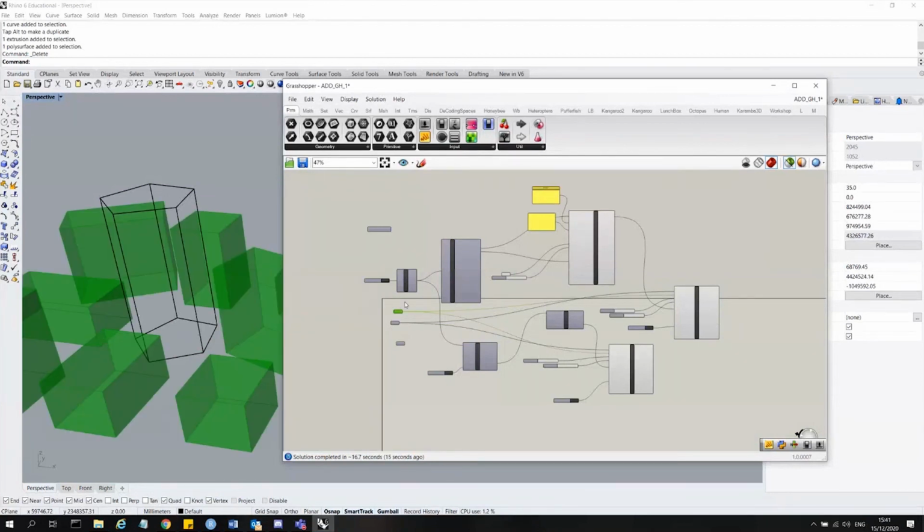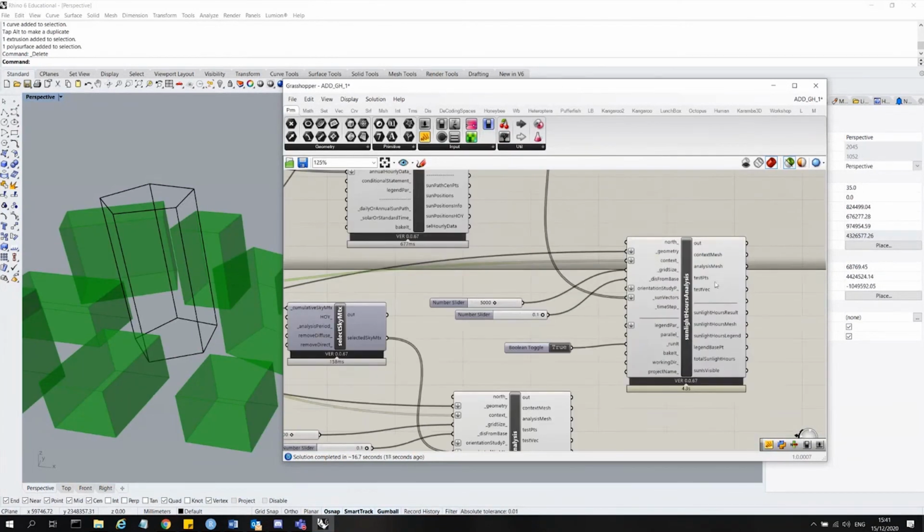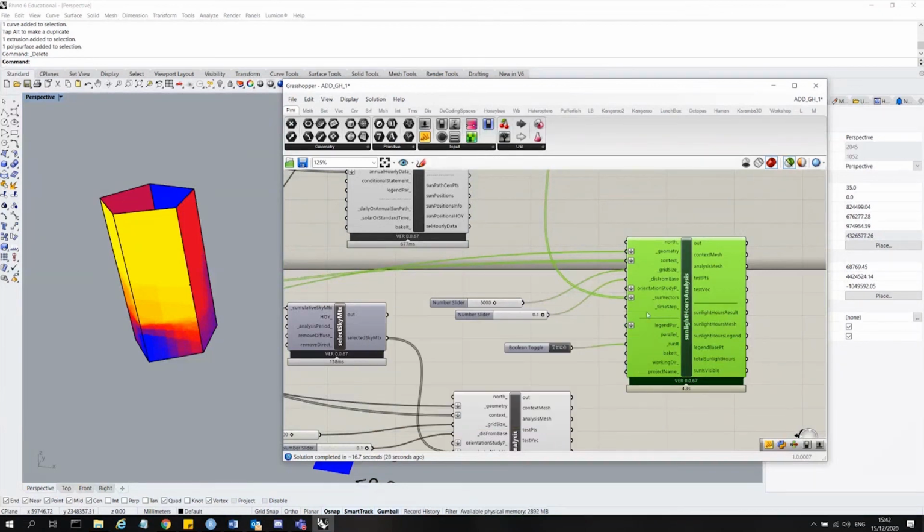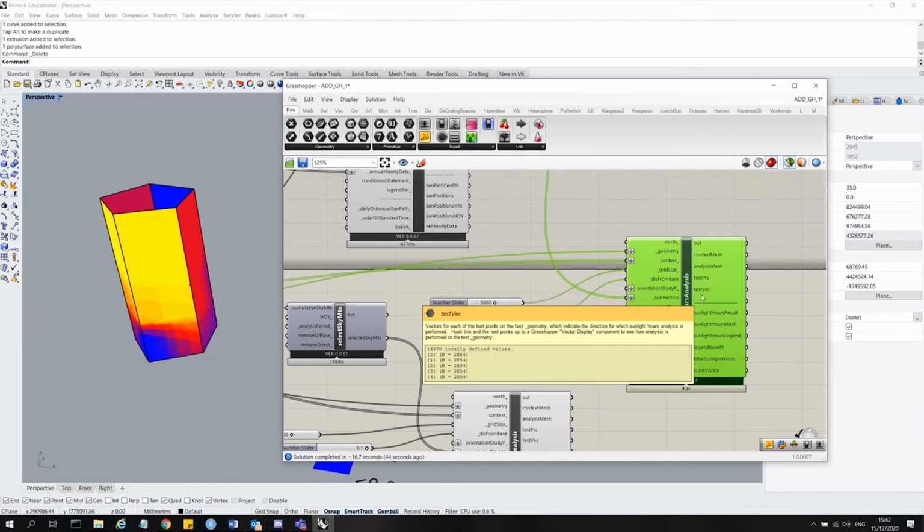As soon as you bring it into the nodes, there's a translation that happens, right? So it's translating the geometry, and sometimes that translation has a problem because the way they've coded it isn't necessarily the best. With flat surfaces, it should work fine because it's easy to translate a mesh to a surface, a flat surface. But if it's a bit curved or twisted, I think that's where the issue is. And there's ways around that. You can explode something and make it into faces and then put it in.